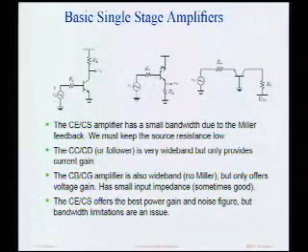You can see the voltage gain from here to here is 0 because I've grounded this node, so the Miller capacitor just appears in parallel with the input. The device capacitance, let's say C pi, is in a sense bootstrapped. That's because the voltage across the nodes are almost equal, so very little current flows into that capacitance, and therefore it's very wide band. Another way to look at this is the input impedance is highly degenerated, and so that feedback, the degeneration produced by RL, is basically going to reduce the input capacitance.